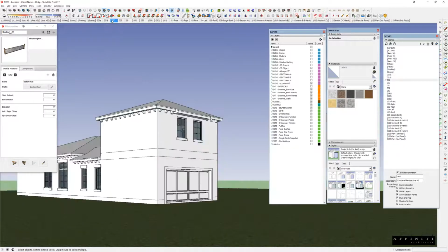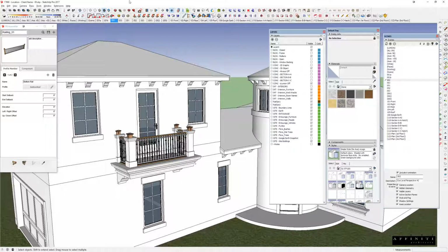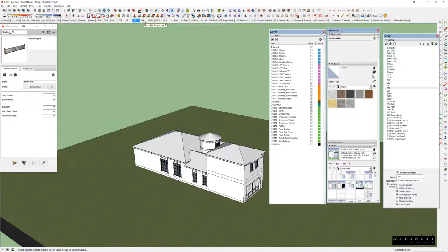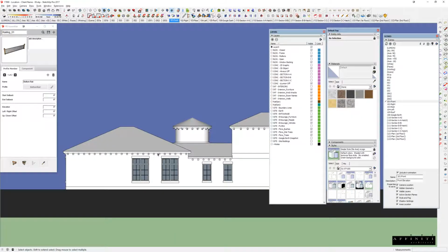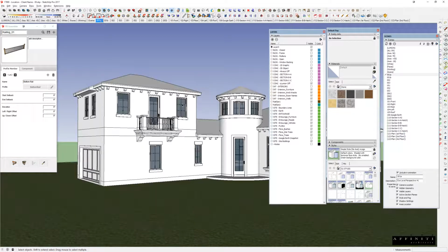Again, the bad piece is I would have to come in and do that for scene 2. If you're crunched for time, scene 2, you don't see it, so you could ignore it. The only bad thing is if you go to scene 2 and then move around, then you have both railing options on. Not a huge deal, it's just something to be aware of. Your scene 3 you would adjust, and you just have to adjust all the ones in which it was visible, including, say, your elevation images. You'd have to do a right A and a right B, but it's the exact same process that we just showed right here. So that's how you would do different railing options.